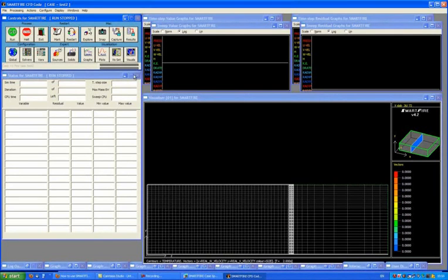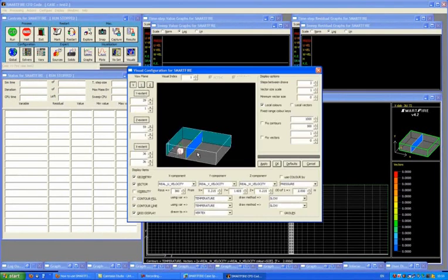First thing to do when you're examining a CFD simulation is probably to set the visual that would be most appropriate for you. The default one is very seldom a very interesting cut plane, and in this case it would be more interesting to move the cut plane through the fire so that we can see the early evolution of the fire effluent and development. I'm also going to change the output to contour fill of temperature and then move the cut plane through the center of the fire.